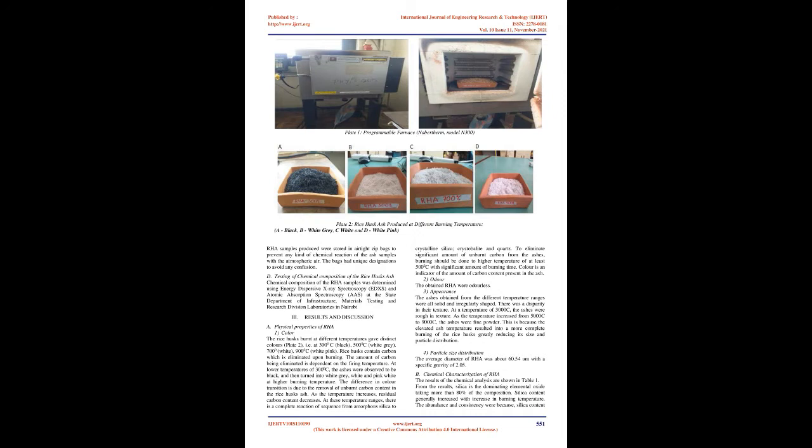Della et al., 2002: RHA presents silica in distinct phases, that is, amorphous, quartz, cristobalite, and tridymite, which is a gradual transition from one phase to the other as the burning time and temperature increase. Gonsalves and Bergman, 2007, showed that the properties of the RHA depend on the ecological circumstances of its origin, soil chemistry, fertilizer applied, type of rice, as well as the burning process. This study is aimed at analyzing the chemical and physical properties of the RHA in Kenya, a case study on Mwea RHA produced under controlled burning with burning temperature as the only variable.